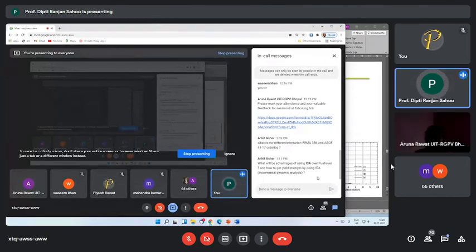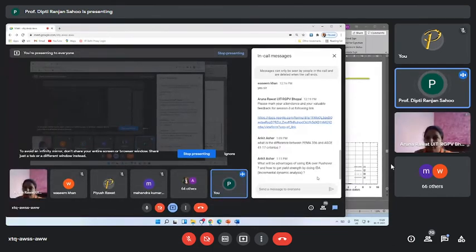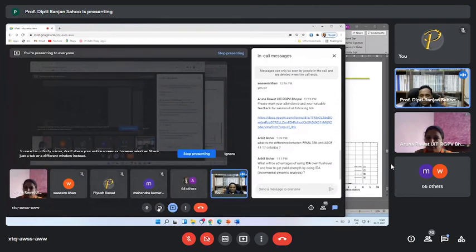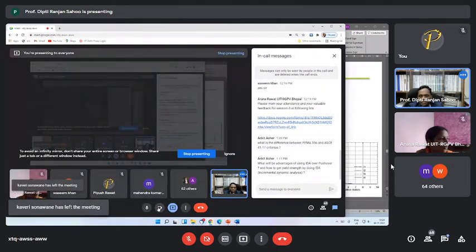It is mostly done to do the collapse assessment of a structure. As I said, we always design the structure for the design basis earthquake and check the stability for the maximum considered earthquake. In incremental dynamic analysis, you keep on increasing the time history PGA or spectral acceleration until your structure collapses, and from that you get a confidence about what probable PGA will cause the complete collapse of the structure.